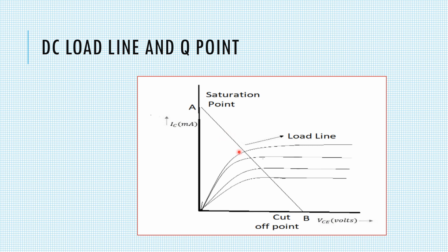When the load line crosses the horizontal axis, the current across the transistor is minimum, the transistor is said to be at cutoff, passing only a very small leakage current, and the entire supply voltage appears as VCE.